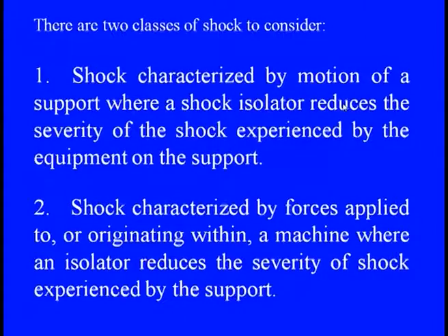One, the shock is characterized by the motion of a support, where the shock isolator reduces the severity of shocks experienced by the equipment on this support. So this is one way. And second, the shock can be characterized by the forces applied or originated within the system, where the isolator reduces the severity of shock experienced by the support. So both characteristics can be used straightaway.